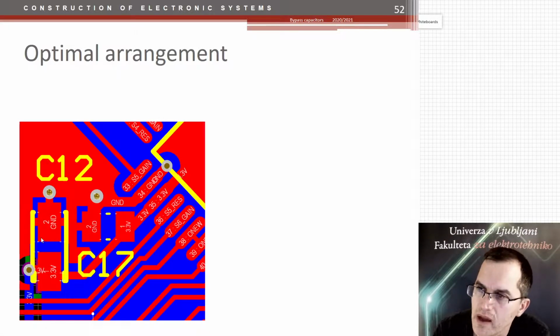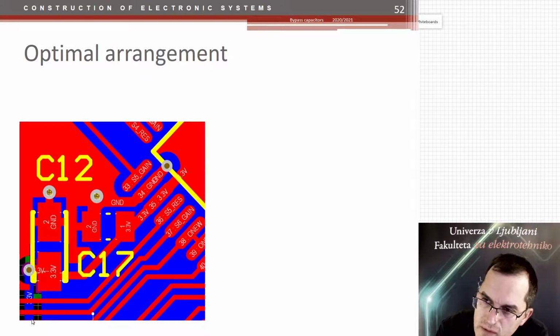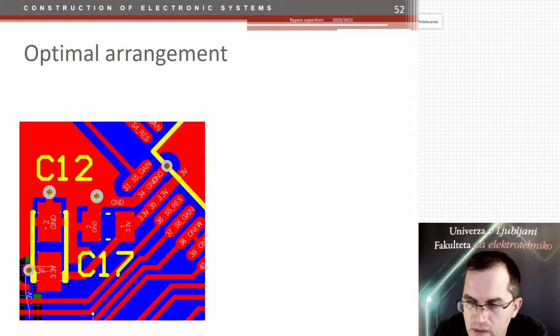So we have a tantalum capacitor, we have a ceramic bypass capacitor. The 3.3 volts is the closest there is. There are two wires, one here, one there, connecting the ground connection as well. And we have power connected from the 3.3 volt connection from here, first to this bulk capacitor that also stabilizes the parallel resonances because it's not the highest quality capacitor.